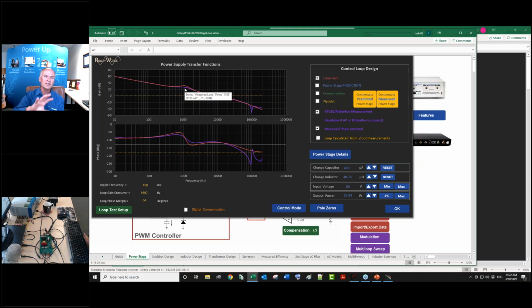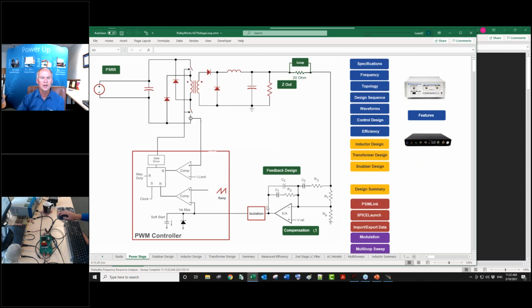Vorperian has actually even come into our program here, and he's given us his latest calculations of Q. We've added proximity loss modeling, and we still always miss the Q. And we miss the Q for a very good reason: every model out there assumes the output of the error amplifier is DC.